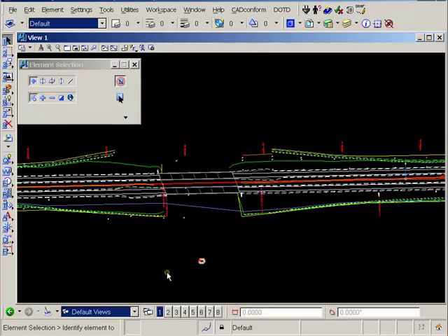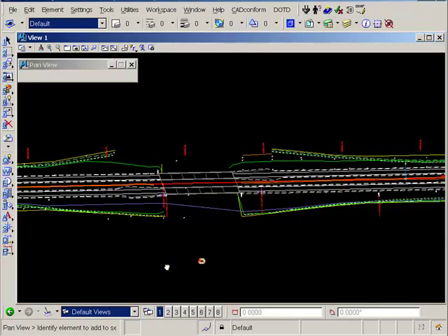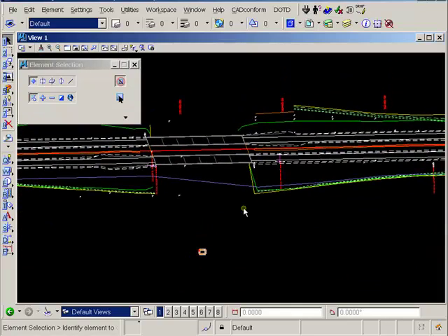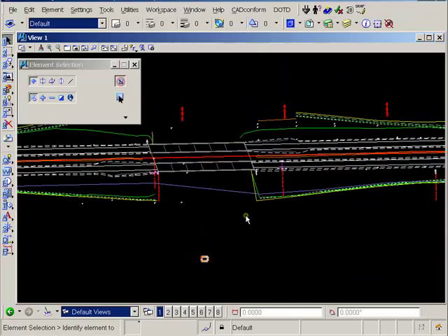Again, I will issue the Fit View command and fit all graphics in the current view. Now I can see that the survey and border files are in the same area of the drawing file. Again, just use the reference file move command multiple times to locate the border near the correct portion of the survey, and then use the Fit command to see the final graphics. I want to move the border near the project center line at the replacement bridge location in the survey file.